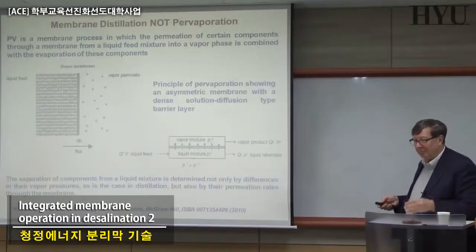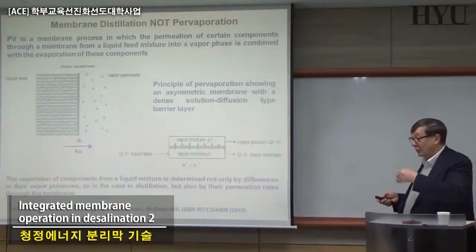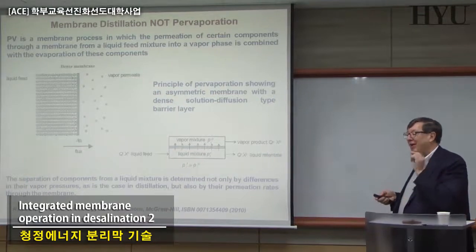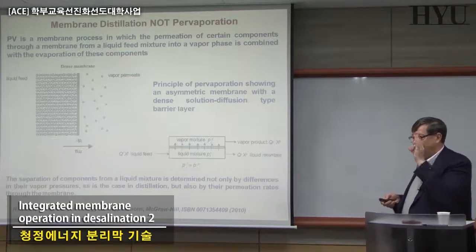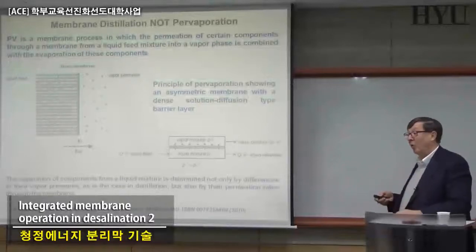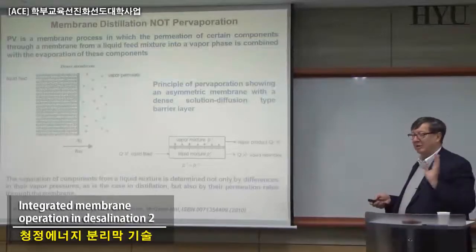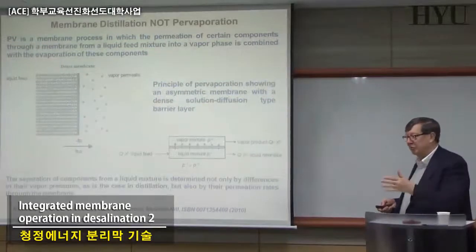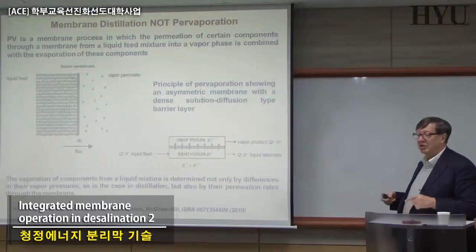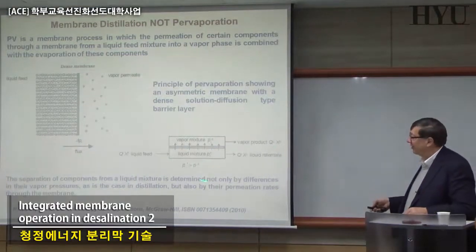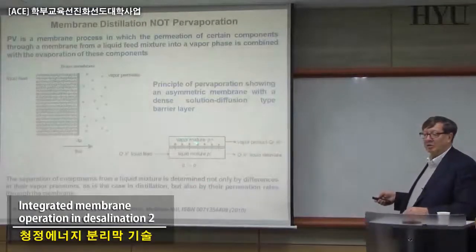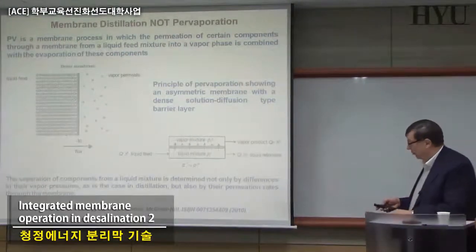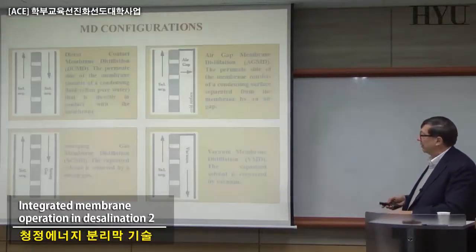It's not the same. The mechanism is totally different, and the consequence is that in membrane distillation, only vapor is going across. The membranes are microporous, and the mechanism is hydrophobicity, which just acts as an obstacle to the penetration of liquid. In pervaporation, the species just dissolve, and you will have a very similar equation to the one that you have been learning in gas separation. But that will be something we will eventually discuss later.